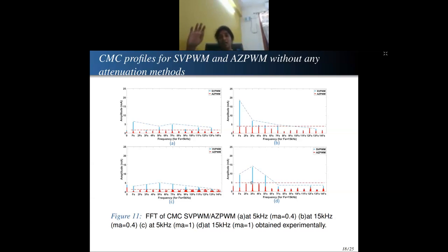The PWMs cannot have control at higher frequencies, because what are the higher frequencies? They are our rise and fall time components. Rise and fall time components cannot be controlled by PWM methods. What you can control is where the PWMs have an effect. You can change the PWM effects only at the switching frequency multiples, FS and its side harmonics. This is what we have control over. So if you use PWMs as a solution, they can reduce the switching frequency multiples.